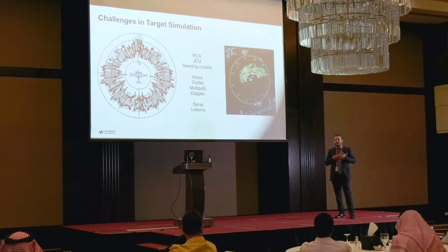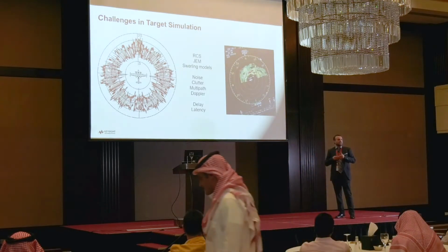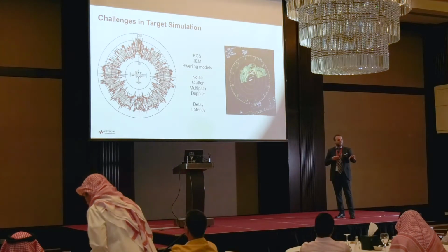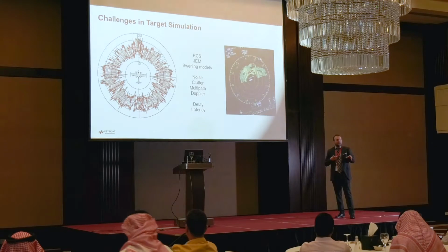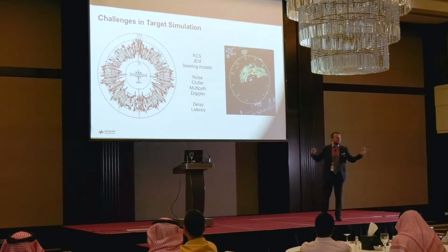And within all of this, we need to adjust the delay of our signal, so latency. With radar systems, we often talk about the latency of the return, and that's primarily for embedded EW systems. It's very important. If you think that all of this RF energy is traveling at the speed of light, 1 nanosecond is 30 centimeters.